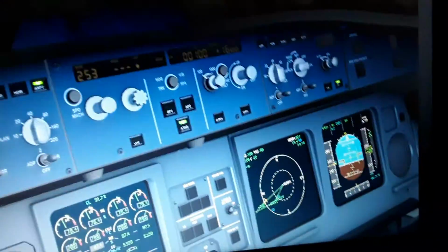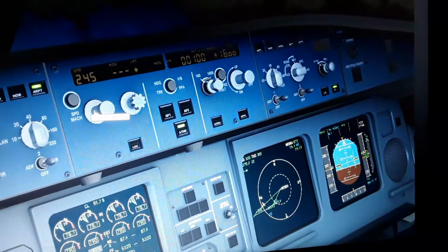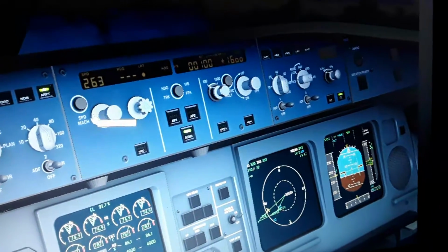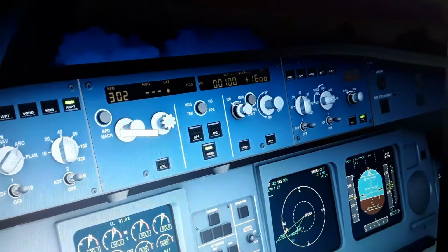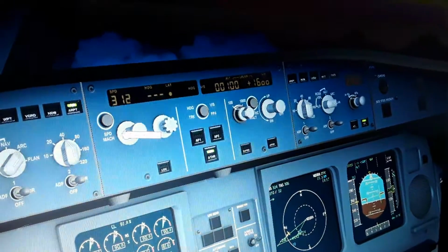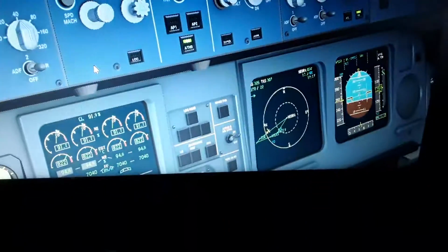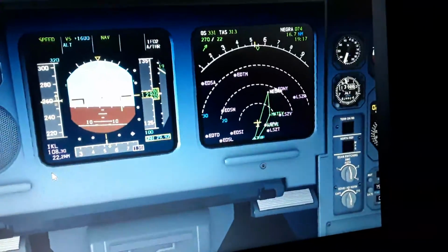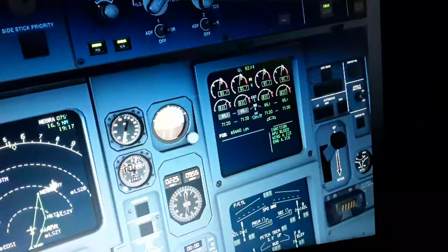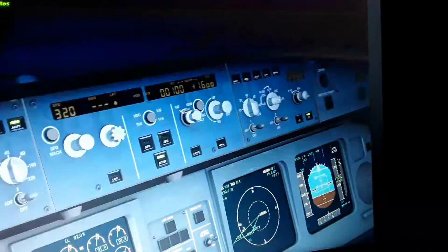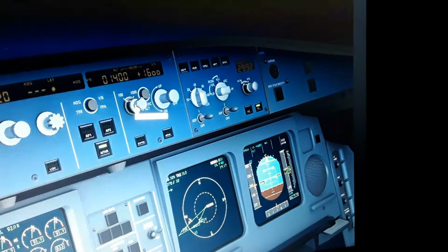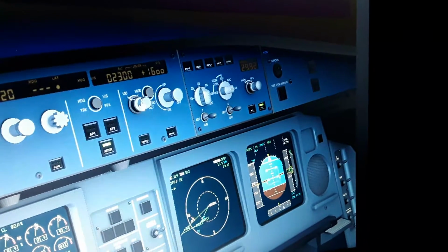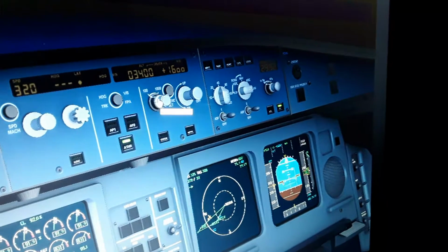It's a heavy aircraft, so maybe I'm using more airspeed from the flight control unit. Here is the airspeed section of the autopilot. So we have 19 more minutes to go for this flight. So I'm gonna make a fast expedite climb right now. So I'm gonna use here the altitude, which I forgot to set to 25,000 feet.